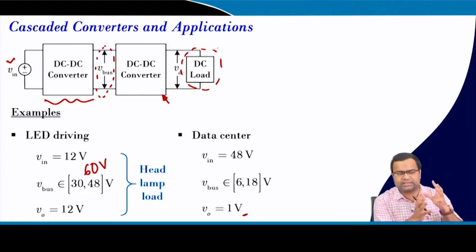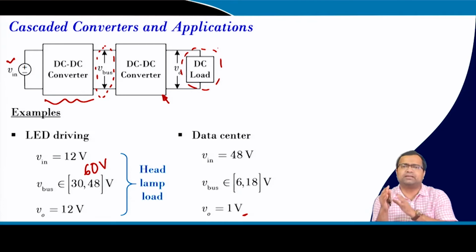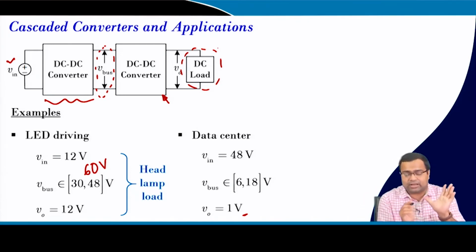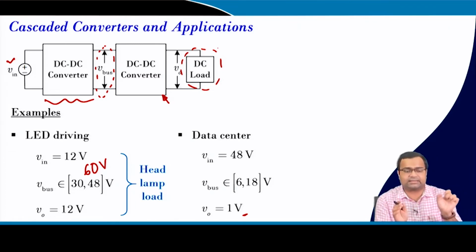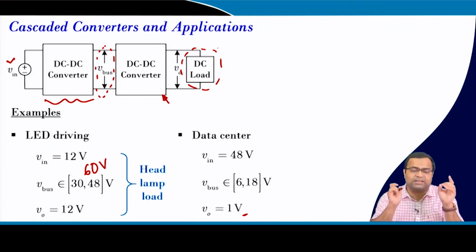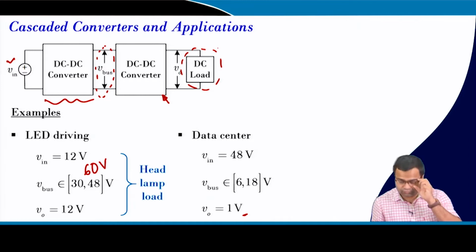And the high bit switch cap architecture can be used at the input side to step down the voltage, and then it can be just simple multi-phase DC-DC buck converter. But all this architecture, but two-stage architecture is still considered to be an effective choice, because we can optimize the intermediate bus voltage, and in that way we can improve both performance and efficiency of this two-stage architecture.